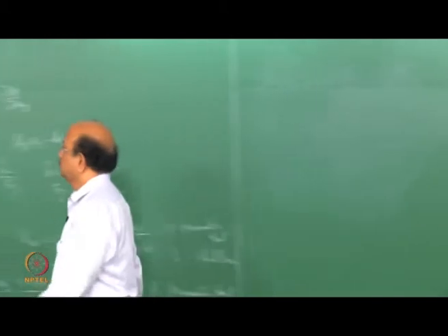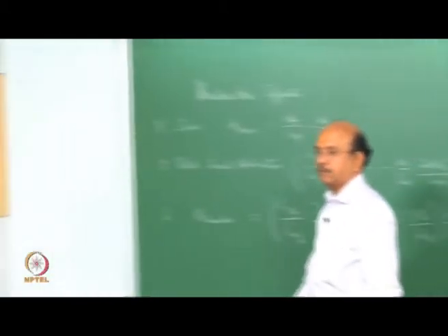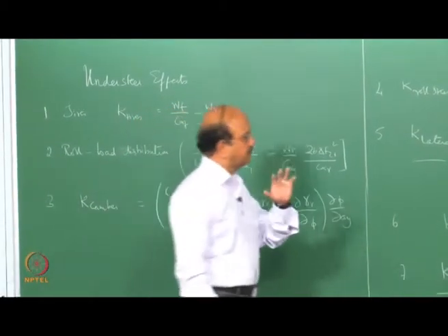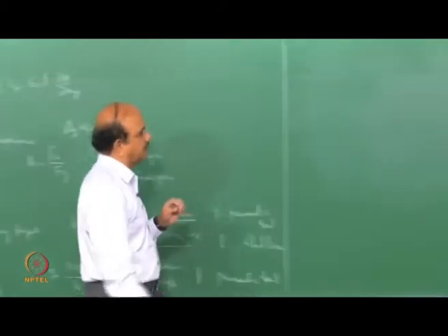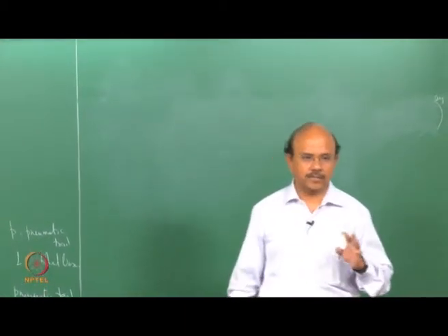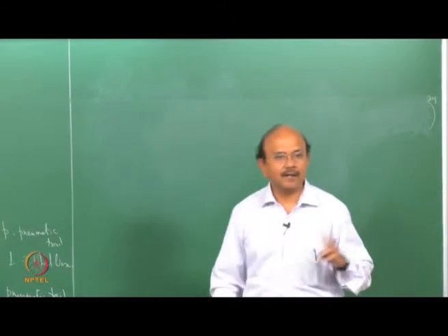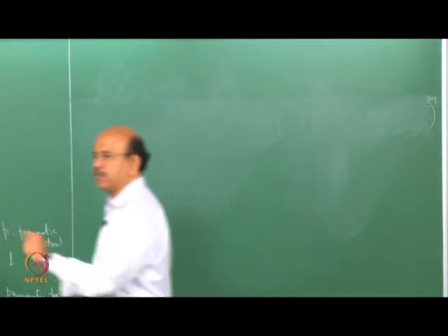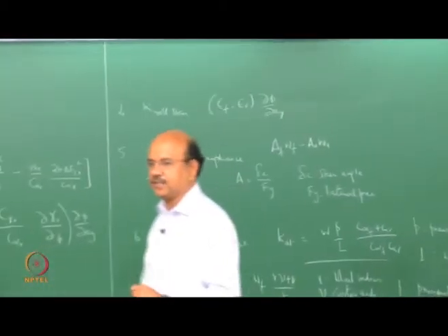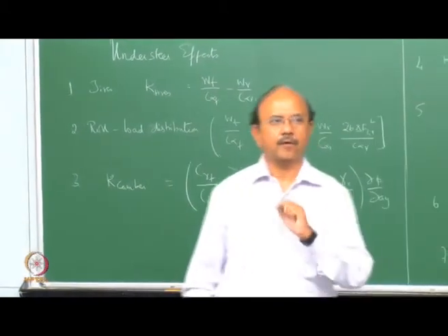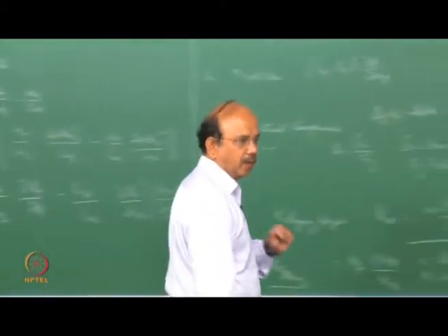And all these roll steer, etc., are they derived only for the steady state turning case, or is it general? Yes, that's a good question. We had started on this. Understeer and oversteer, all these things are derived for steady state. So that's why we introduced what is called transient understeer and transient oversteer. This becomes a very important test for subjective evaluation.